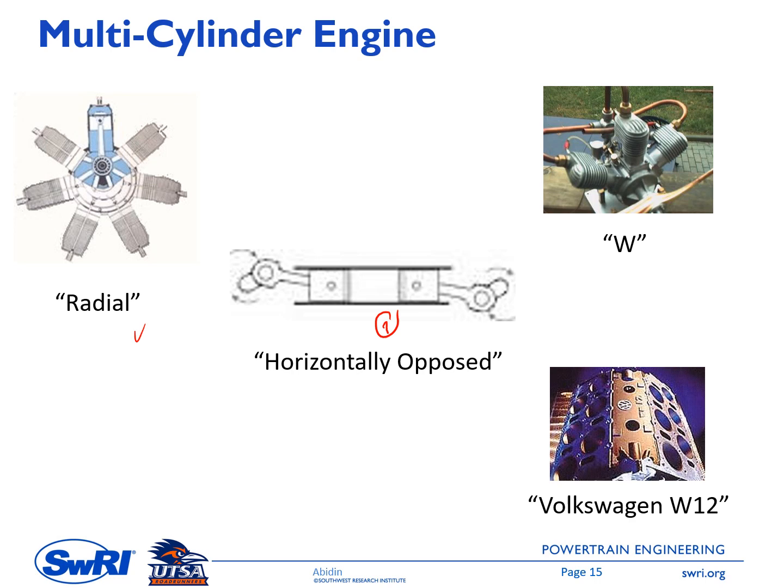So you can see here we have 2 pistons, and the cylinder head is only 1. So 1 cylinder head is shared by these 2 pistons, and this is the crankcase. Once again, this is very popular in large 2-stroke engines used for marine applications or power stations. And this one is a Volkswagen, so W12. It has 12 cylinders, and it is used by Volkswagen.